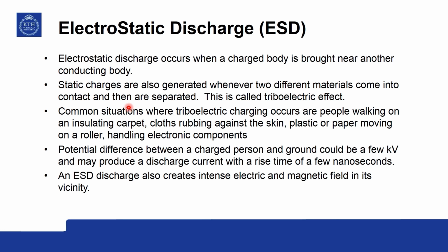Now, ESD is a big problem in paper industry and plastic industry whenever you have situations of material passing over rollers, because it can produce micro dimensional pinholes into the materials. So, they have to control electrostatic discharge at any cost.